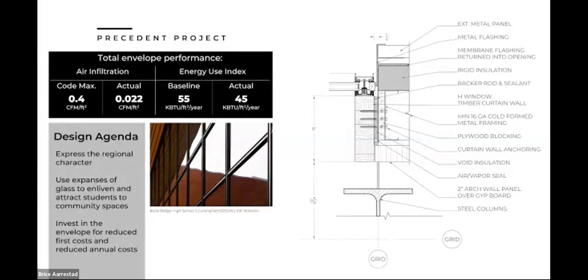I met with the architect, the team that did the commissioning, the blower door testing on this a few months ago, and he said they came to the site to test the air tightness and performance of the building. They came to the site expecting to use 5 blower doors to pressurize the building and see how it would perform. He said the equipment was failing. It was too tight. They had to reduce to 1 blower door and like half another one. They had to cover some of the fan. So they were able to pressurize the entire school building with 1.5 blower door fans.